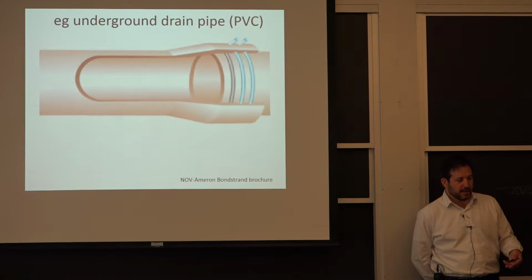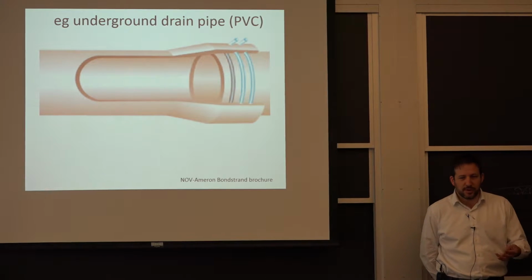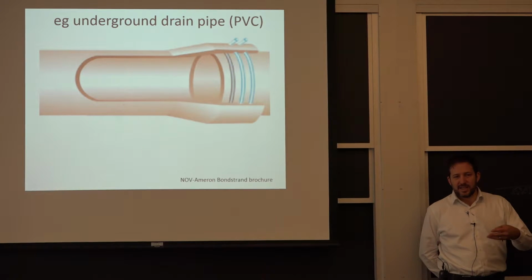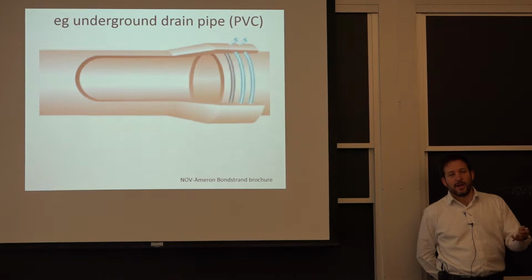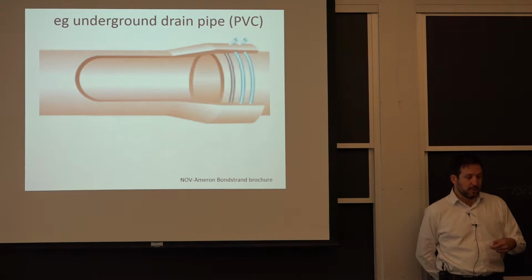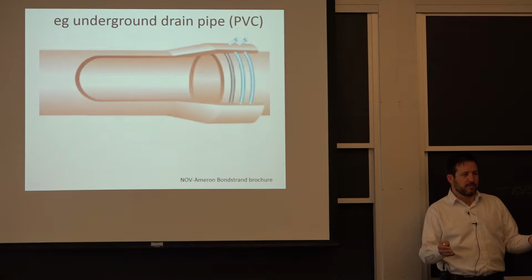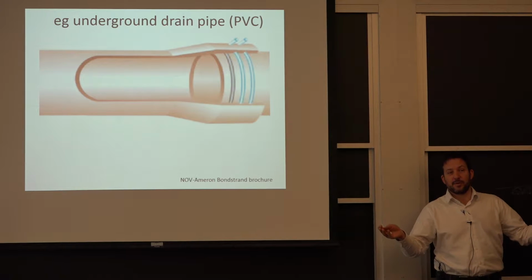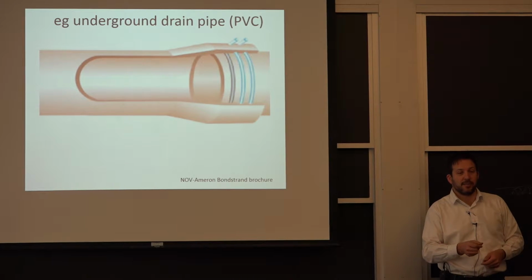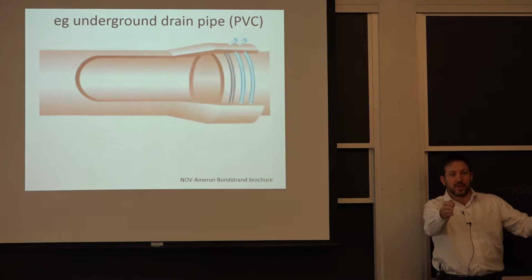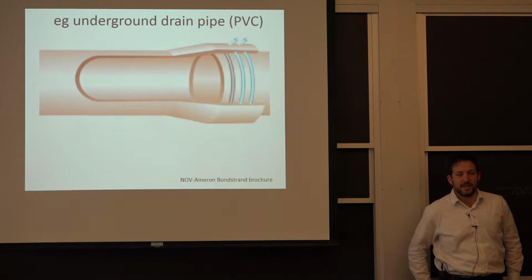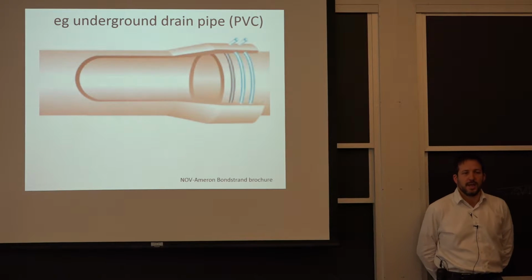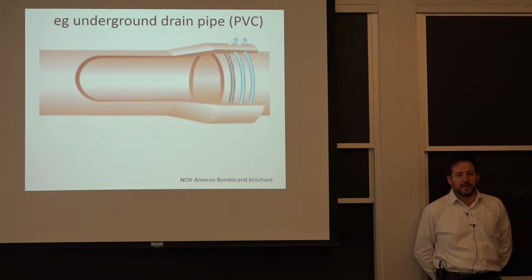But this is a topic that I think is very interesting. When you start using plastics, they expand and contract more with temperature variations. So a lot of the issues, with the rigid plastic, like those fire sprinkler lines, you don't worry too much about with metal. Let's say the metal is going to stretch 3 millimeters over 12 feet. That's not a problem. But if now you have 3 times that amount, maybe it won't go too well. It will actually create a lot of bending if you have too much restraint on your system. And that's something we've seen a few times.